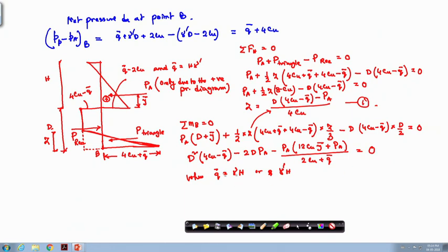So, you solve this D from this equation, then you increase it, find D from equation 2 and increase it by 22, 30 or 40%. Okay. So, this is the equation to determine the depth of a cantilever sheet pile in cohesive soil.